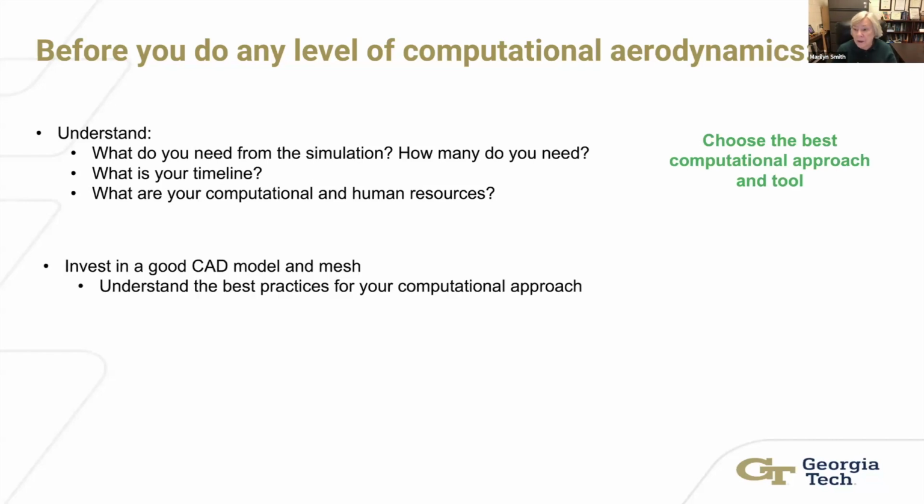Invest in a good CAD model and mesh. If you don't get a good mesh, even with some of these panel codes and lifting lines, if you don't pick the right number of points and everything, you're not going to get a good result. Okay. Use best practices. Look up to see what other people have said are good practices.